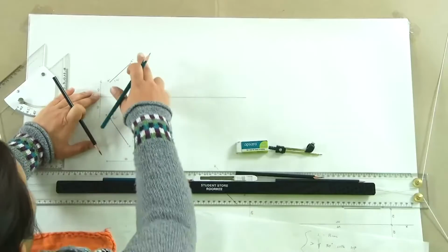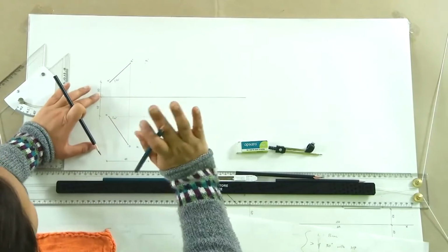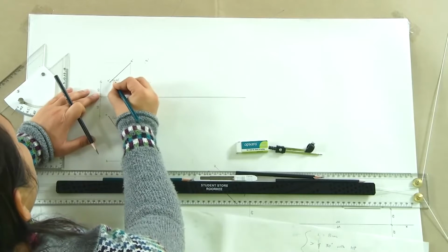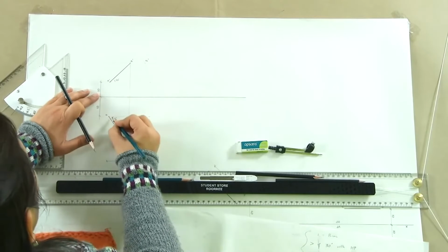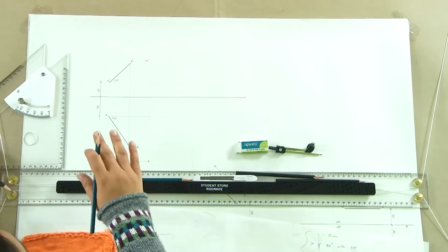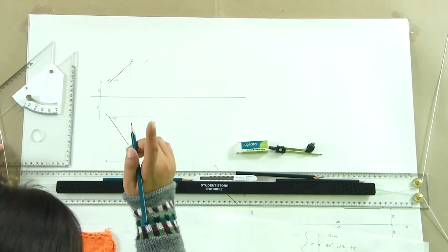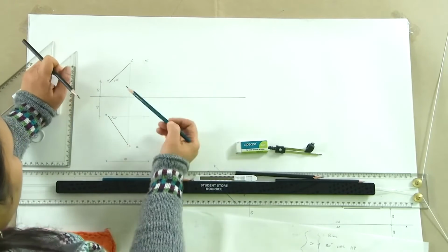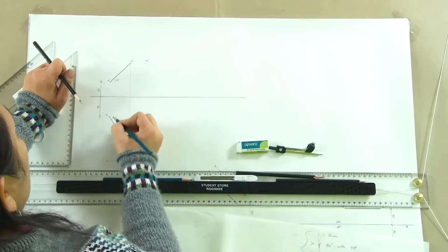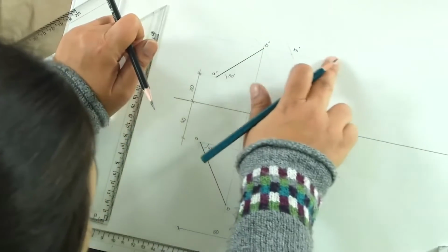So, we might be given the horizontal trace and the vertical trace of the line which is inclined at certain angle, and in addition to that, we might be given the angles that the projections make. In that case, the same process will be done, but in a reverse manner. So, what we would do here is, we will draw the traces at the given angles, say alpha and beta, and then draw the locus of it.